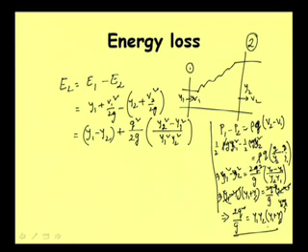So using this relation, twice Q square by G is equal to Y1 Y2 into Y1 plus Y2. Now here we have a term Q square by twice G, but this term is twice Q square by G. So just replacing that part, we can write Y1 minus Y2 plus Y1 square minus Y2 square, and as 2 is here, to have another 2 there we will have to multiply it by 4 and divide it by 4.